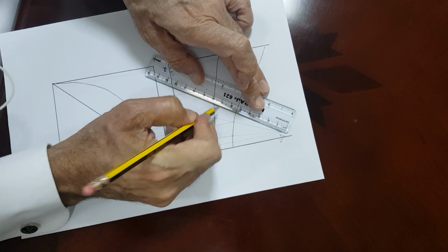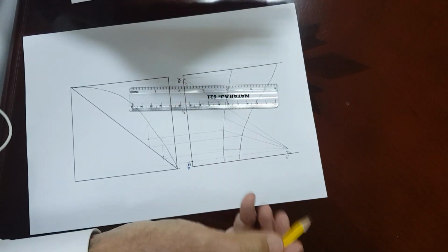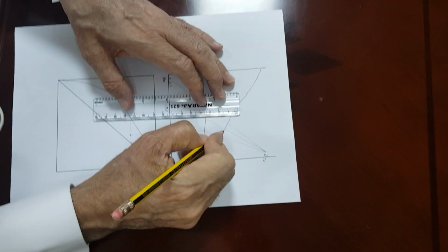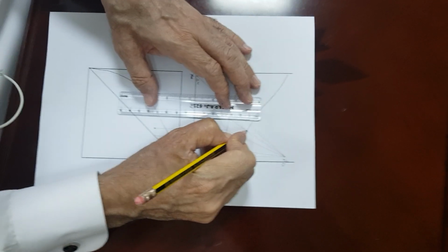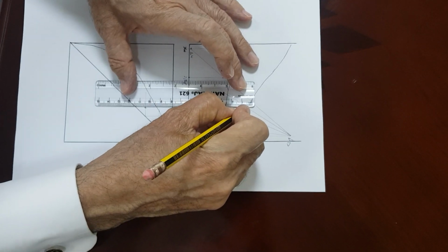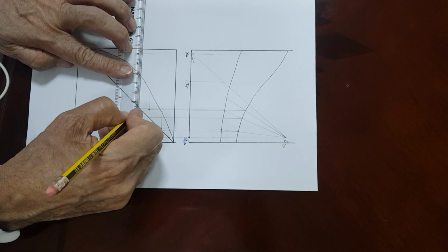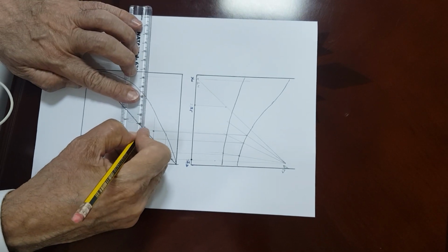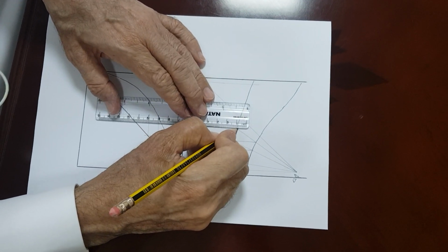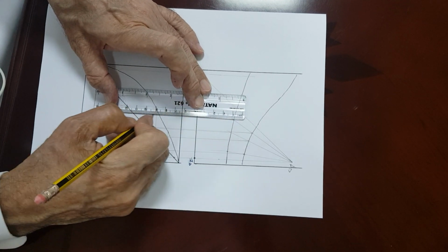nonlinear operating line. So again, drop any random line from delta D, and take the first intersection with the vapor line, drop a vertical line to the Y versus X, to the 45 degree, then a horizontal line, and you drop another vertical line from the liquid intersection and drop it.